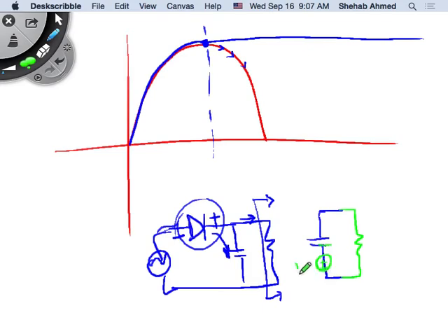And the voltage source has a value equal to the initial capacitor voltage, right? So you have now a circuit with a source, a capacitor, and a resistor, and you do the solution. The solution is A e to the minus t over tau, right? It's a first order differential equation where tau in this case is equal to RC, not L over R, right?